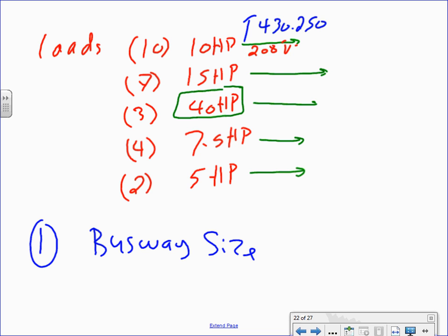If you go there, you're going to find the full load amps for this one is 30.8, and multiply it by 10. Why did I multiply by 10, gentlemen? Derek, we multiply the amps by 10 because how many machines do I have this time? 10. Piece of cake. The 15 horsepower is 46.2 multiplied by how many? 7.